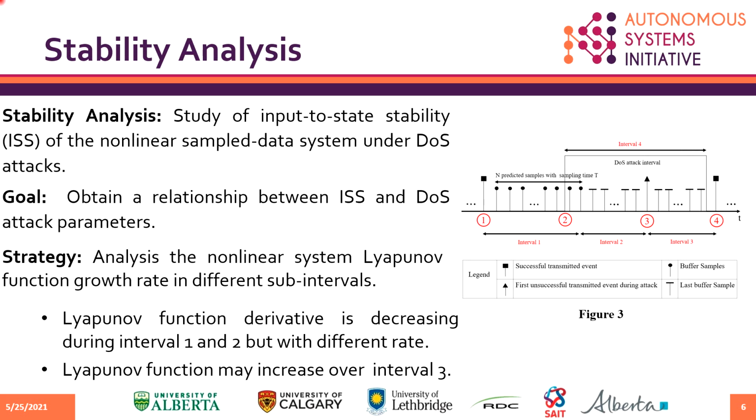We are interested in studying input-to-state stability of nonlinear systems under denial of service attack. This strategy is based on analyzing the Lyapunov function growth rate in different subintervals. For example, by using tools from multi-rate sampled-data control, the Lyapunov function derivative is decreasing during interval 1. In interval 2, there are no new triggering events, and therefore the system remains stable, although with a different convergence rate. In interval 3, the event rule is violated. However, the feedback signal cannot get updated due to the presence of the denial of service attack. Therefore, the Lyapunov function may increase over this interval.